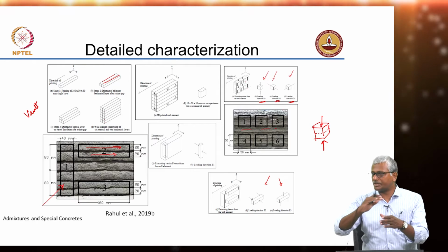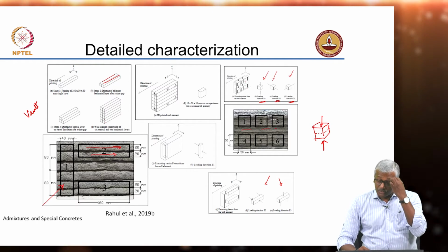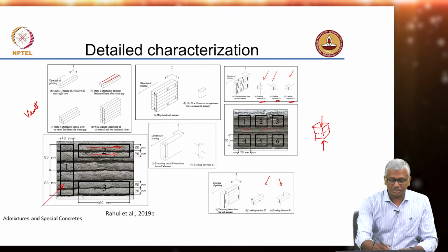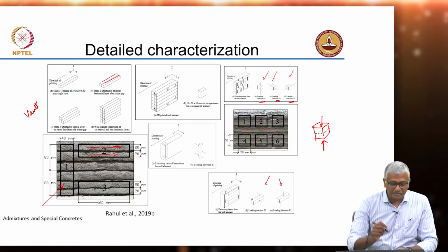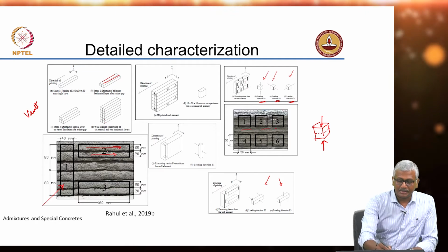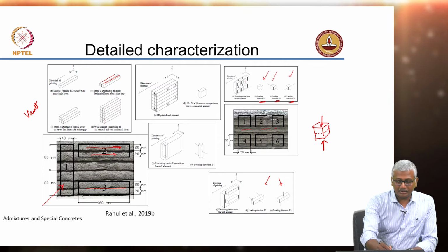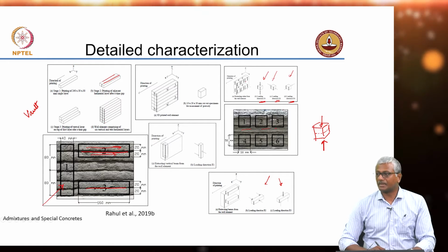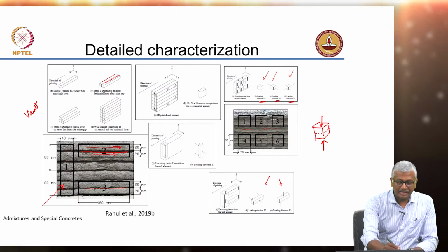So, you have to prepare the top by grinding it or capping it and so on, right. So, the cube gives you that flexibility of not having to prepare the specimen. Similarly, for flexure also, prismatic specimens are obtained from the vault. These prismatic specimens were different. For instance, the type 2 and 3 specimens had the interface exactly in the center, okay, whereas the type 1 specimen had interfaces at several locations.